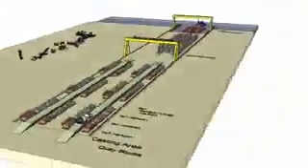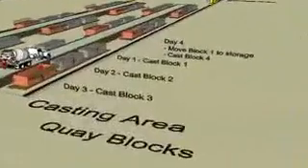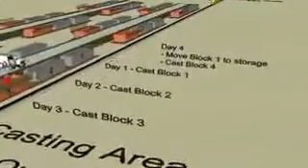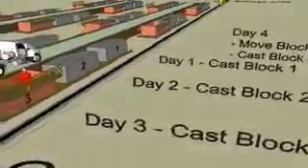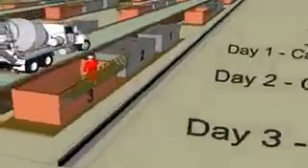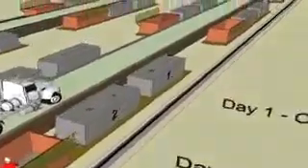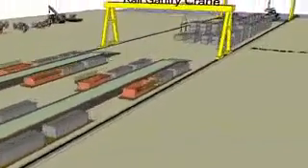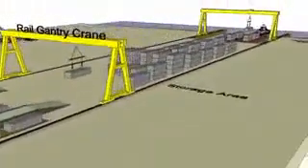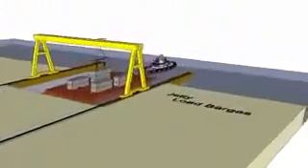Precast yard. Full-scale sample castings are constructed to demonstrate and document that all the requirements of the concrete and the execution of the work are fulfilled using the actual methods and performed by personnel that will carry out the future castings. One concrete component of each type is produced for approval. The approved castings were retained in a dedicated area for quality assurance purposes.